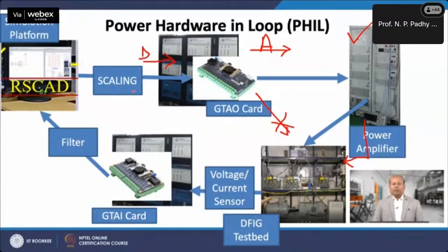Digital simulators like the RTDS, which employ the electromagnetic transients algorithm, can mimic the network reaction in a time step as quick as 50 microseconds. The interfacing DFIG device, that is part of the network, requires the exchange of voltage and current between the digital simulator and itself.